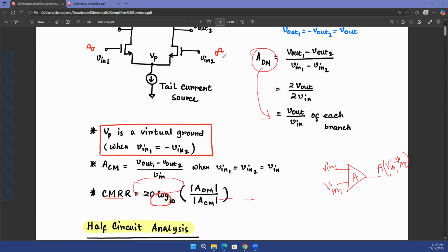And most likely it is at the input side itself, because the two inputs, V1 and V2, go to the gates of the two NMOS transistors. And you know that looking into the gate of the NMOS, you see infinite impedance. And you know that looking into the two inputs of the op amp, you also see infinite impedance, ideally. So you already get an intuitive sense that this is going to be the first stage inside my op amp. Question?